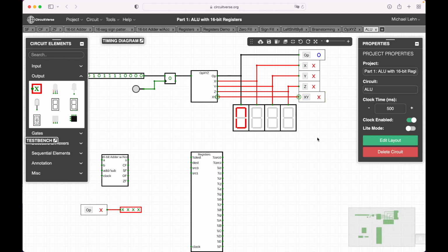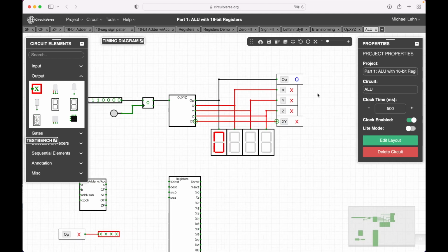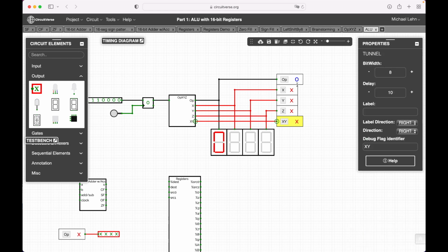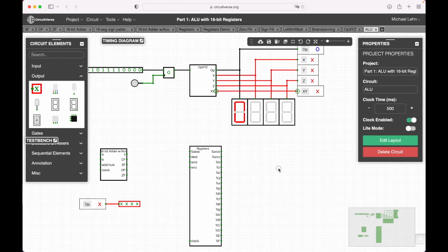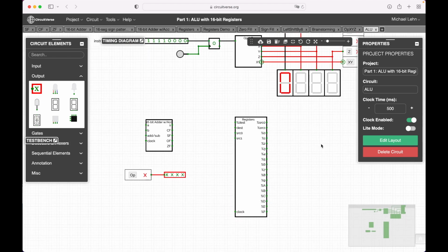Okay. Requires some thinking how arrangements can be done nice. Make sure that this XY device has a bit width of 8. All others should have a bit width of 4. Then we also need some simple access to this A, B, and to the choice whether we want to add or subtract something. So we also connect this with some devices, and then here you have to be careful that A and B are 16 bits, each of them, and this add or subtract is 1 bit.